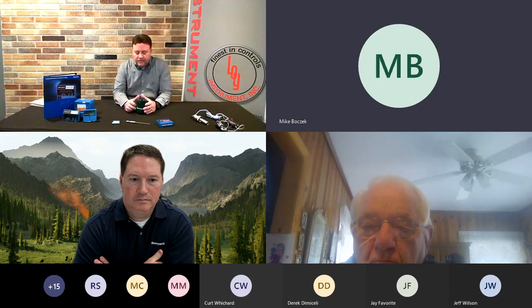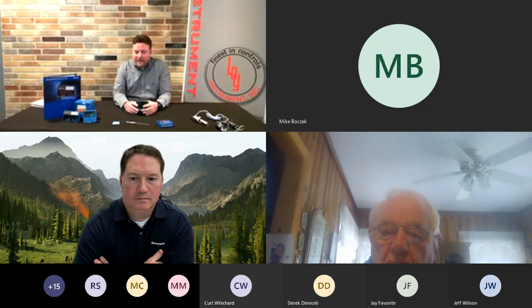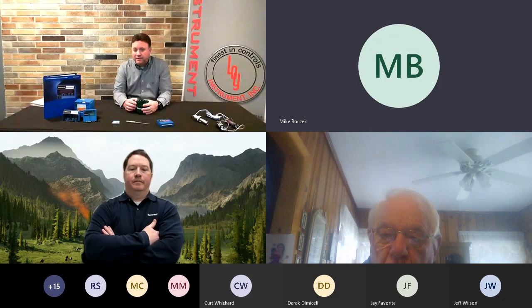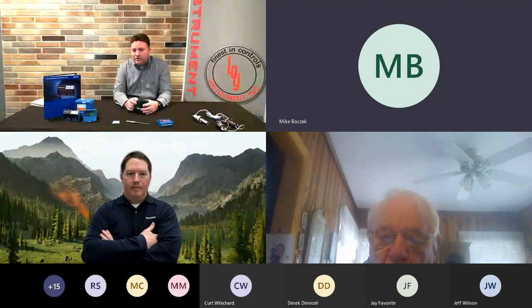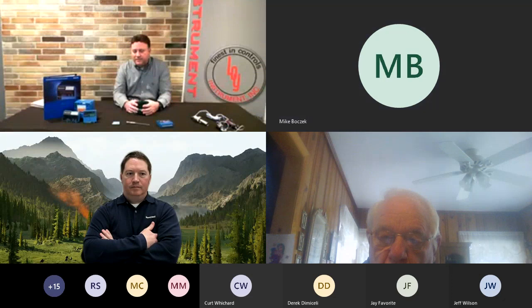Yeah, so in applications where the standards allow for the burner to be relit once the flame is lost, a 0.8 second flame amplifier will allow you to relight once the flame is lost.